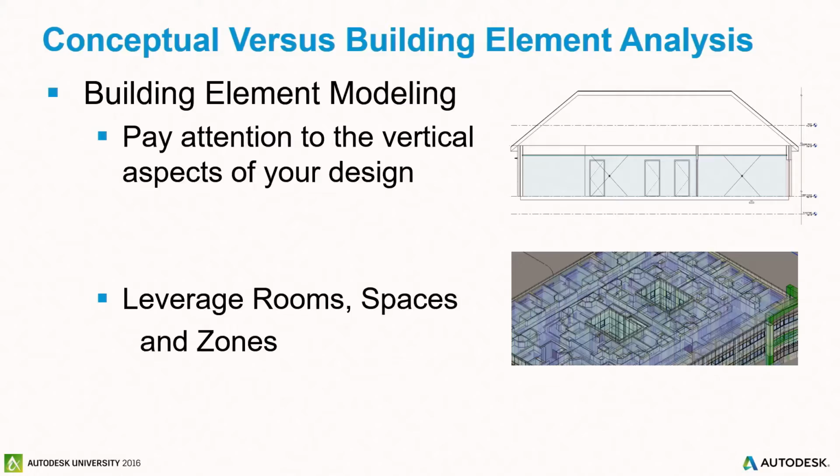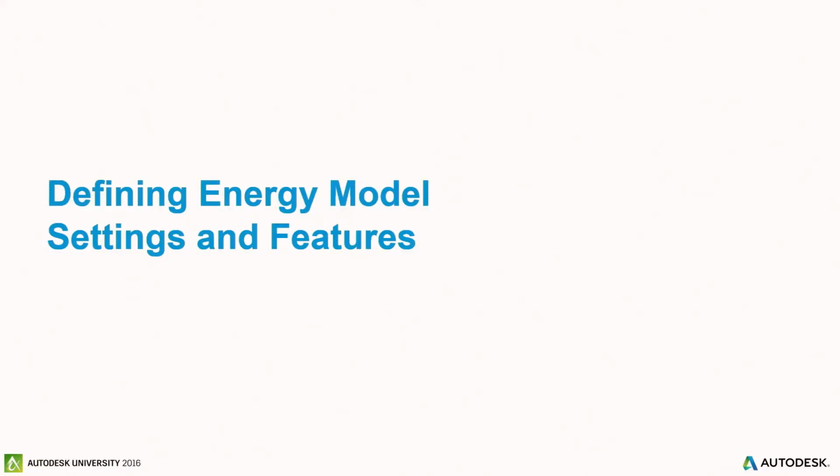And another step that we don't get enough of is people actually using rooms, spaces, and zones for something other than as a mechanism to tag an area. You have to make sure that you're putting these things in correctly, because on the MEP side of things, I'm going to use that space against the room and pull that information from the room, but I'm also going to use spaces in interstitial areas, chases, and everywhere else to help me do a better model. That make sense?